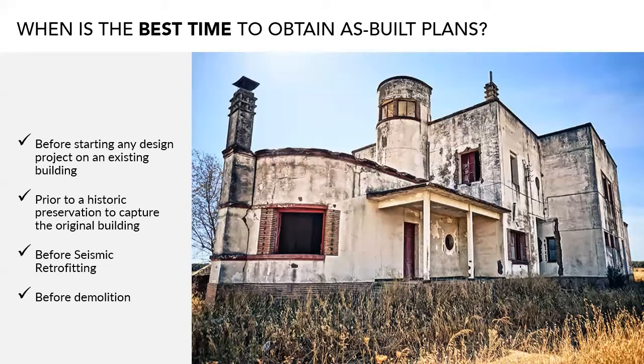There are also cases where you'll be working with maybe the historic review and they'll require as-built plans to be created. Most engineers will want a fresh and accurate set of as-built plans before they begin maybe a seismic retrofit. If you're working on a teardown project, some building departments even still require you to submit as-builts of those structures that are being demolished.